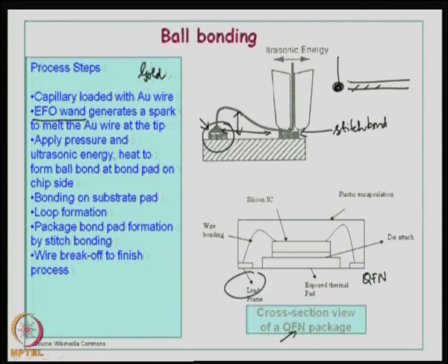You can see this is the area where the heat will be dissipated to the substrate. So, this is an exposed thermal pad. There is a die attach material, a glue that bonds the chip to the substrate. Then you have the wire bond here. Wire bonding is done on both sides, peripheral. This is the die and then this is the encapsulation. This part is the encapsulation.